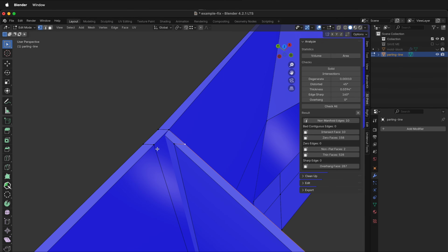1, click a vertex, View, Frame Selected. Zoom out a bit. 2 for edge mode. Option or Alt click to get the whole edge loop. GG, move it into the corner. Select this one, the whole edge loop, GG, just to get a little closer.